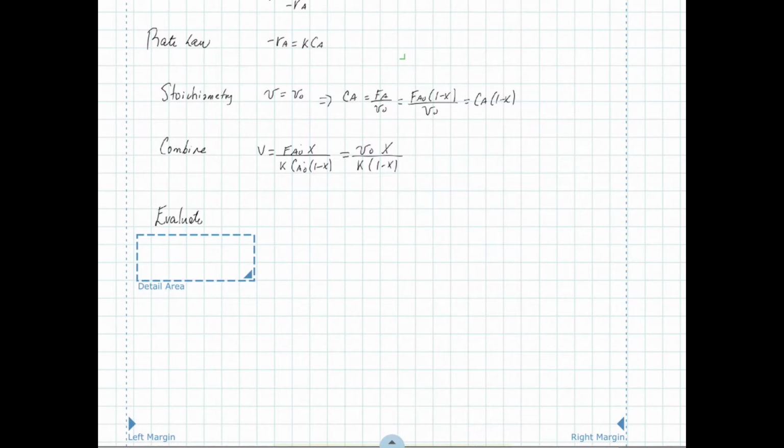Because the information that we have here is just data, specific parameters are given in the condition, there's no data. We don't need to use numerical methods to analyze the area under the curve for a flow reactor, or in this case for a CSTR, the area of the rectangle that we will have in the curve. So here is where you decide what to do. Basically, I think this is one of the most important parts when analyzing and getting the information for a reactor design, that you decide what to use.